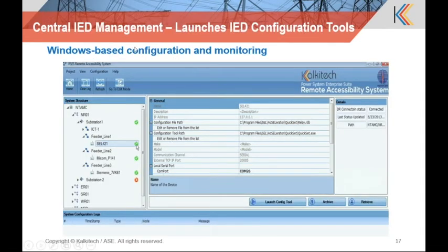So this is a quick view of the configuration tool, the PSCS tool. This is the thick client, a desktop-installable application. You can see it is separated into multiple regions like north, east, south, west. This is basically taken from an Indian scenario, and there can be multiple substations and multiple feeders. Under each feeder there can be multiple IEDs, and each IED is connected to the SYNC 2000. The live communicating status and non-communicating status of the IED are indicated here. The substation is the indication of SYNC 2000 itself, and the feeders with communicating IEDs are indicated here.